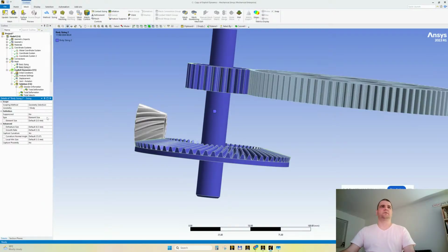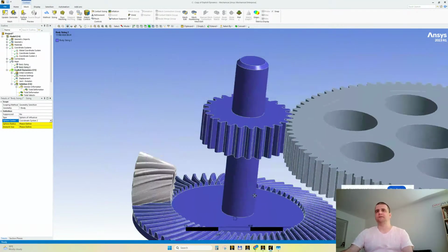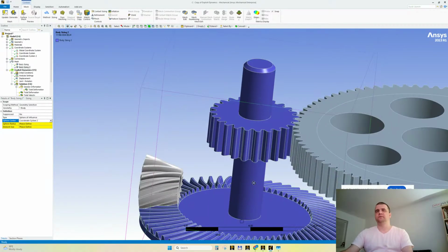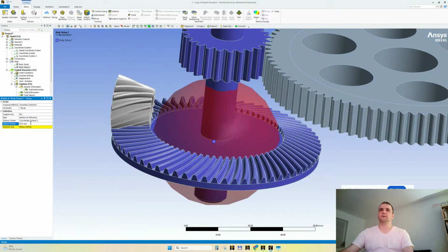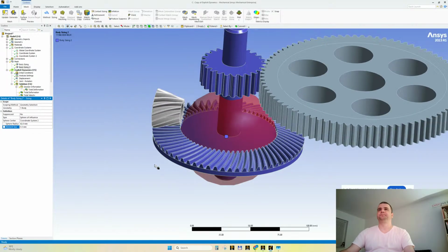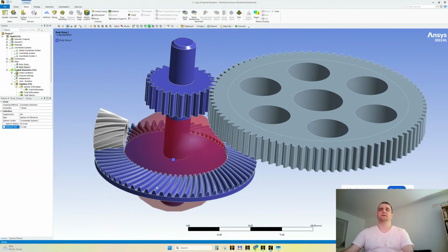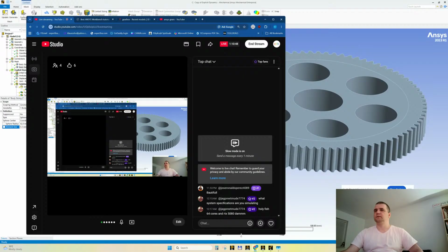And I will say, instead of type element size, sphere of influence, sphere center, the second one. And you will see in a few seconds what the radius of this gear is, around 40 millimeters. Let's say 42, something like this. And again, 5.5. So I would like to make the center, or the inner portion, more coarse in order to decrease the solving time. Any other question? No.